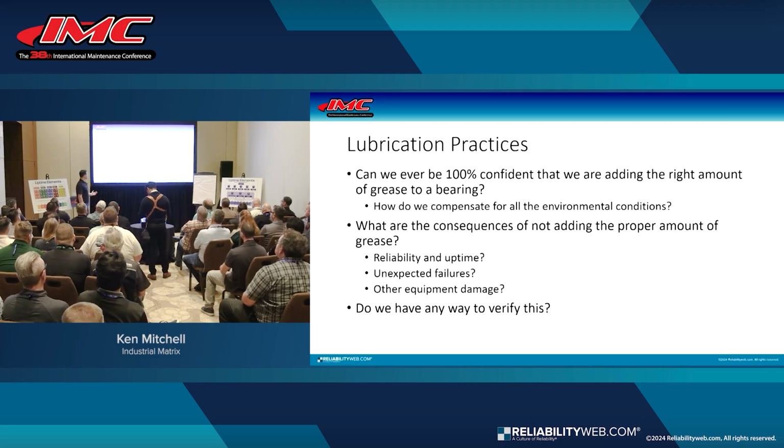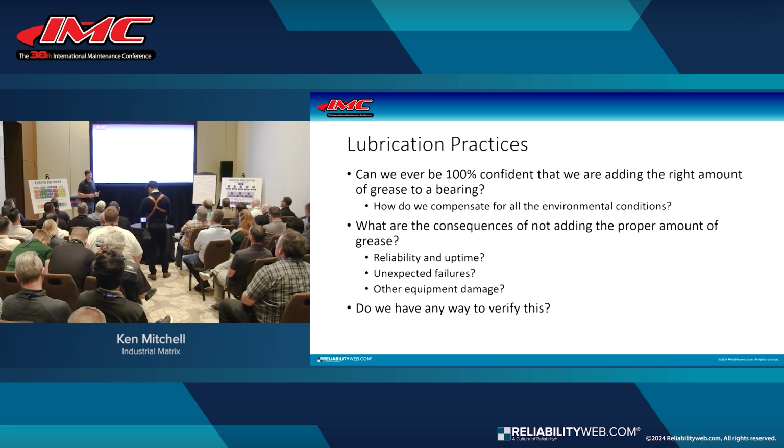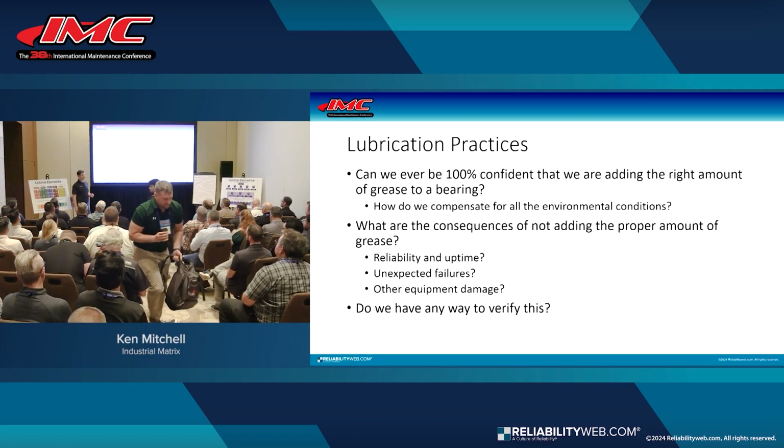So next question is, can we ever be 100% confident that we're greasing a bearing just right? Are we under lubricating? Are we hitting that perfect zone of lubrication? And then how do we compensate for all of these factors? Because there's a lot of factors. Vibration, noise, temperature, they all affect how much lubricant we should be putting into a bearing.